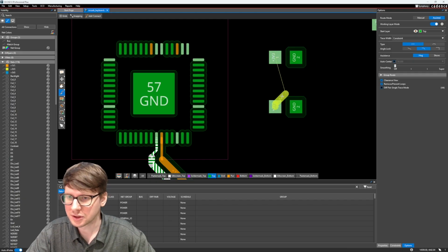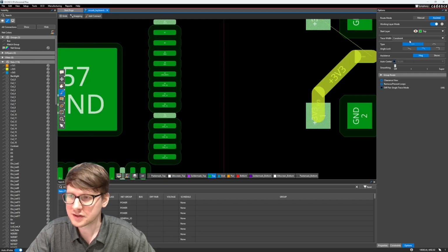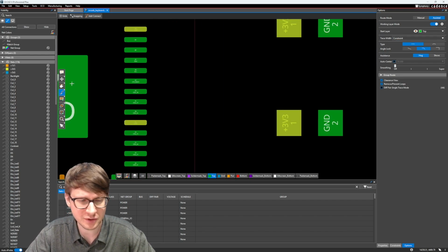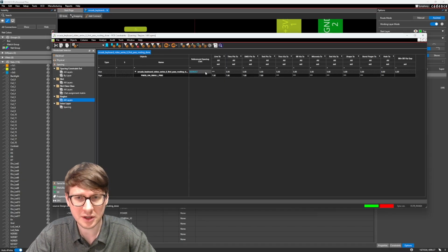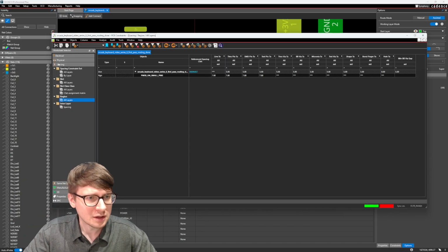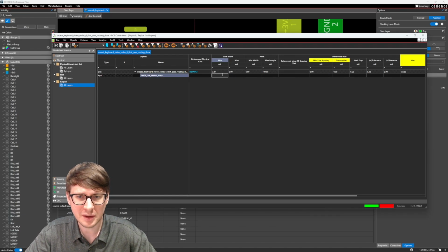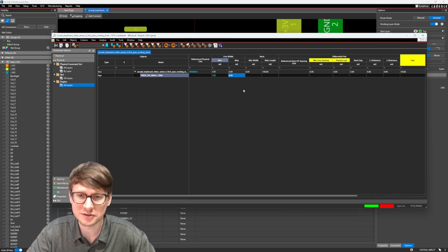And we want to be in our constraint. The nice thing is that one thing you can also do is in this constraint region, let's go to our constraint manager. We can also set a physical region and say that our line width is automatically set to 7.87 mils with a maximum of 0.